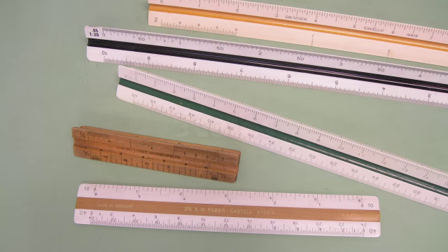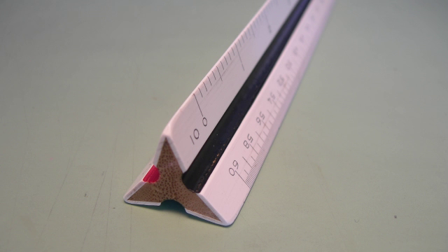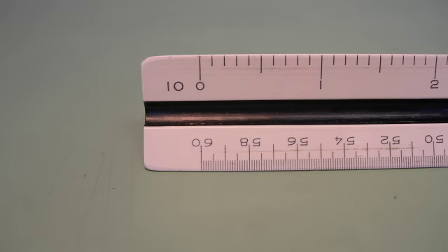It is not always possible to create a technical drawing at its actual size, so a scale is needed to transfer measurements onto the drawing at a fixed ratio of the actual measurement. A traditional engineering scale is triangular in shape with 6 different edges and 6 different scale graduations. The scale graduations on an engineering scale are 10, 20, 30, 40, 50, and 60.